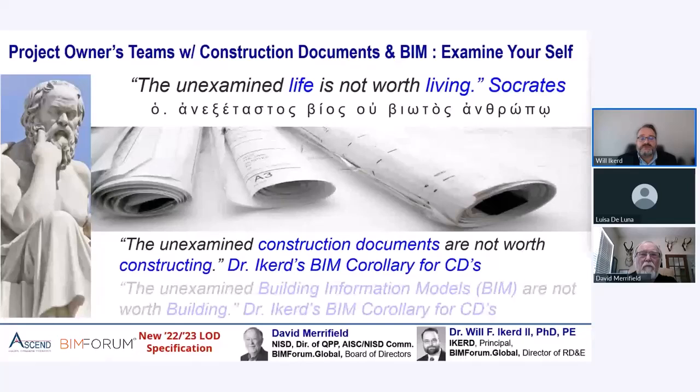And this is one of those interesting elements that the window openings are the domain of the architect. The parapet is the domain of the architect. The reveals, domain of the architect. The bottom of the wall and how it connects to the foundation belongs to the structural engineer. The thickness of the wall and the reinforcing in it belong to the structural engineer.